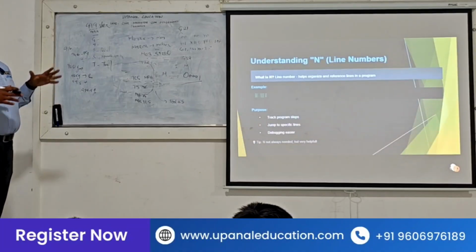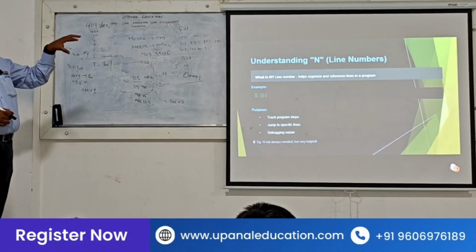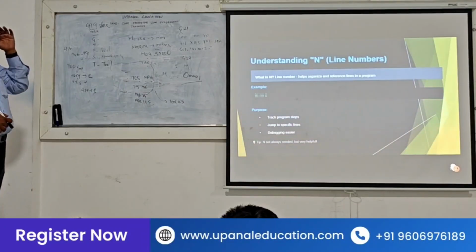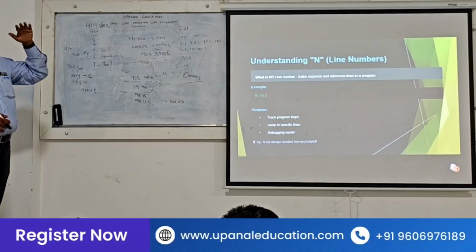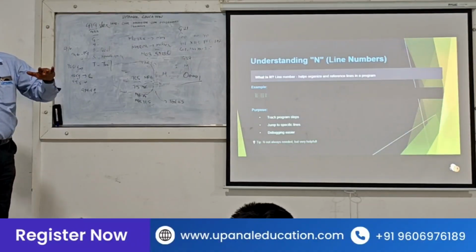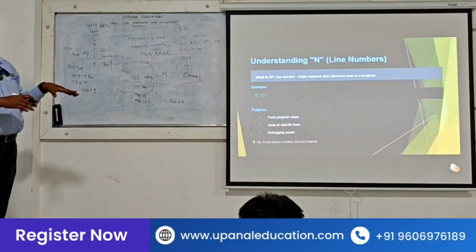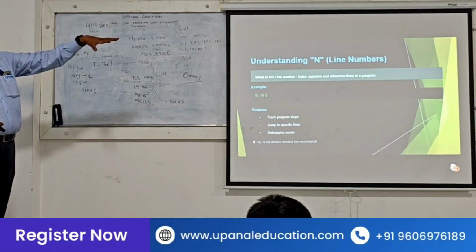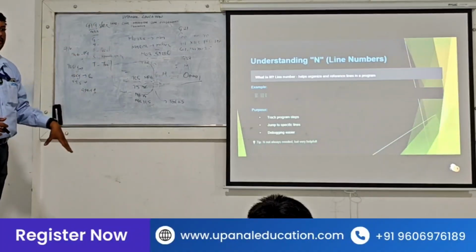On a Mitsubishi controller, we can restart the program from that point. But sometimes if this restart fails, we remember the program stopped at around N52,000. We can enter approximately that value, say 50,000, and restart it from that point.